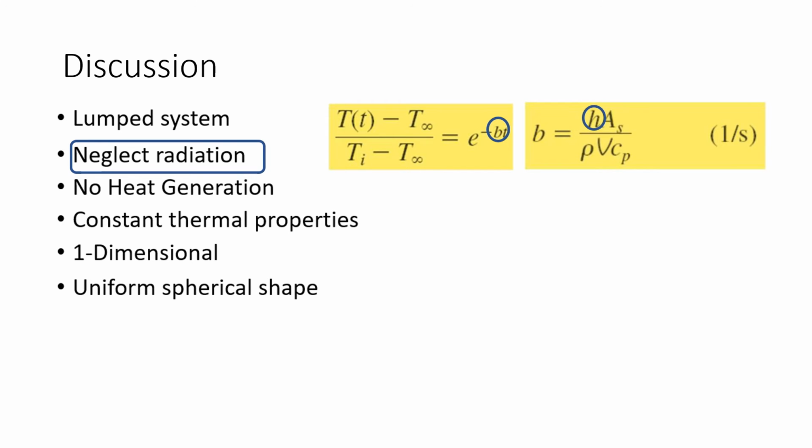And if radiation was involved, I believe H would go up and the overall heat rate leaving the system would increase, and so after the same amount of time, 4 seconds, I believe the temperature would be a lot cooler, closer to the environmental temperature.